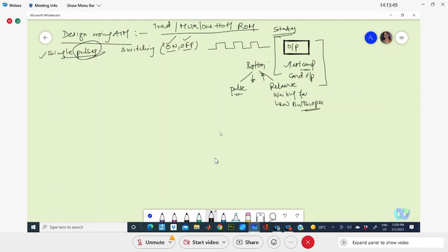So what we are saying is this button signal is not synchronous. It is not happening at equal intervals. Anytime it can happen. Normally in our ASMs, a star or asterisk on top of the signal indicates the asynchronous aspect. Say, if I take this as button, B is the name given to that button, and the star on this indicates that this is asynchronous.